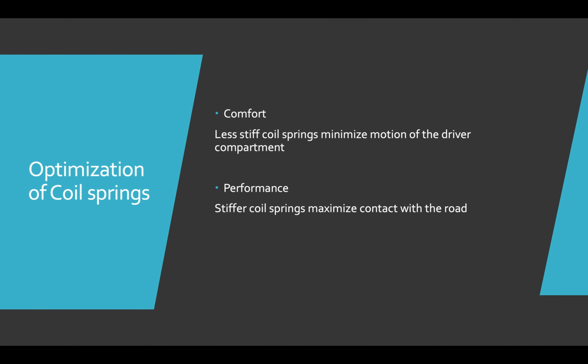Optimization of coil springs. When implementing a coil spring, the designer has one of two things in mind: comfort or performance. In order to maximize comfort, less stiff coil springs can be utilized in order to displace more, hence absorbing more shock and displacing it from the car. If performance is desired, stiffer coil springs ensure maximized contact with the road, as well as increased responsiveness to the driver.